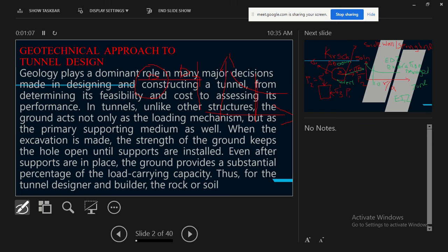while we are here, it appears that in the stress readjustments there is no change. The drastic changes in stress redistribution have stopped. So for all intents and purposes, that can be described as the excavation damage zone. However, the assumptions of these formulas are based on a very good, homogeneous rock, class 1, like a very good rock, so to speak.